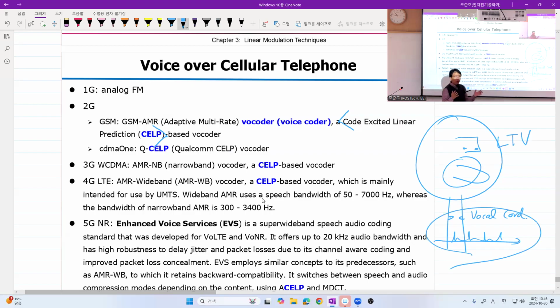So people wanted to compress the voice. So they analyzed how it is generated. And voila, what they did is that, okay, m(t), if it is a speech signal, can be decomposed, in a short time period, into this pulse train, where you only need the frequency and amplitude, and the filter.